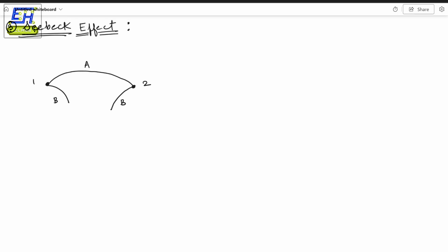So what is observed is that if these two junctions are kept at two different temperatures, non-equal temperatures, you'll actually see some voltage developed across these points. So for example, on this end, you can cool it by keeping it in ice water, and the other one you can heat using a burner.